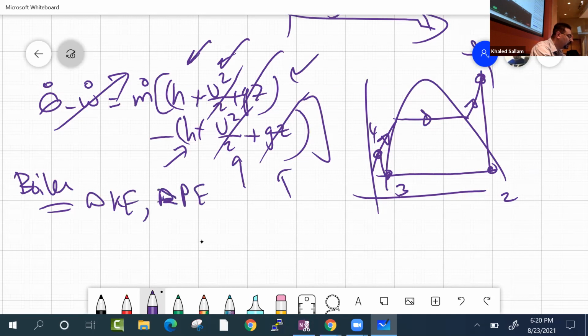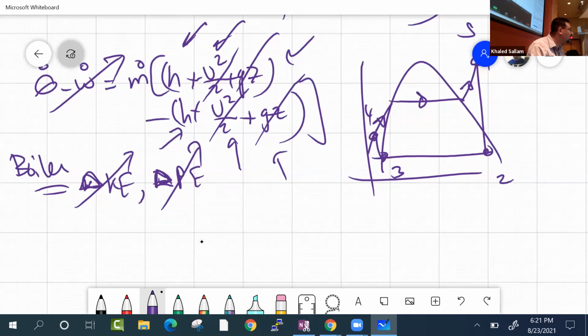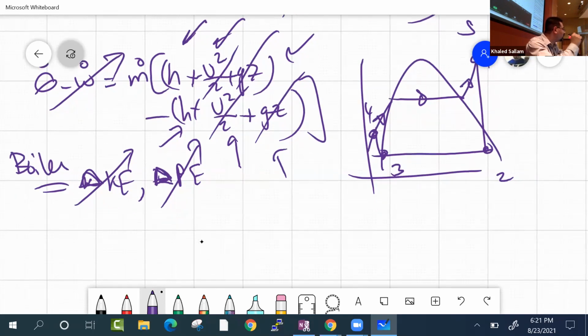Will I be more accurate if I consider those? Yes. But when you are trying to calculate the wealth of Bill Gates, you don't really have to calculate it to the cents, how many cents he got. I mean, yes, you'll be more accurate if you figure out how many cents and you count how many shoes he got and how many t-shirts, but how important is it compared to his actual number? So when it comes to the Q dot added, yes, calculating the delta kinetic energy and delta potential energy will change the number a notch, but who cares?